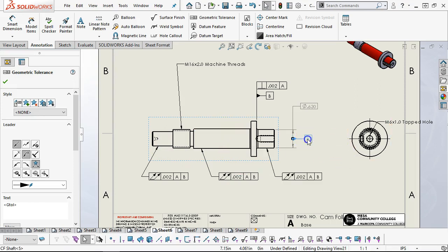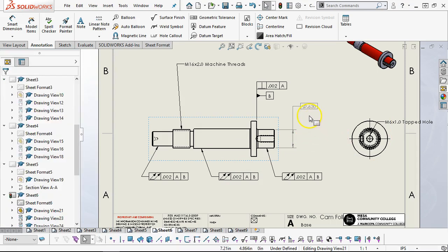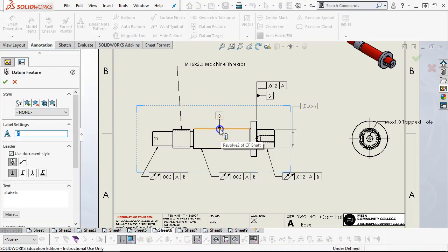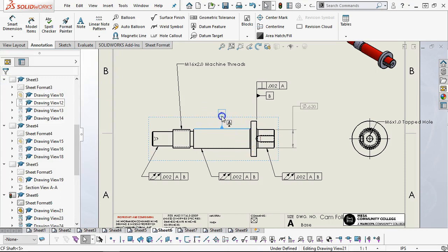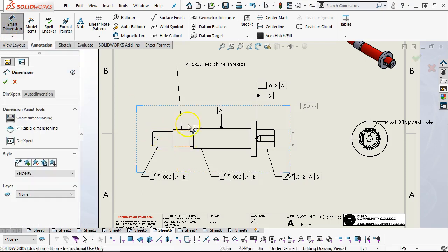All right, so if I'm looking at it from that standpoint, then the 630 becomes a basic dimension, and we're going to end up going over to the outside face, and I need to change that back over to A. All right, so as we go through this, then the smart dimensions, we have the call out, and we'd have to determine, is that going to be a for reference, or is that going to be the actual call out for our geometry. So if we come over here,